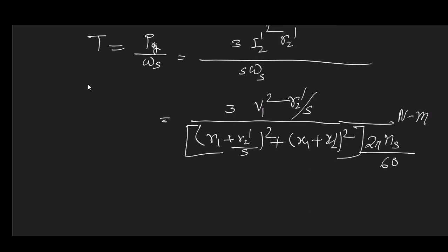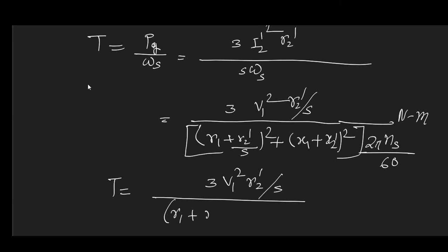But another form is available, that is the torque in synchronous watt. Synchronous watt is nothing but an expression of power. Whatever is your air gap power is known as the torque in synchronous watt.